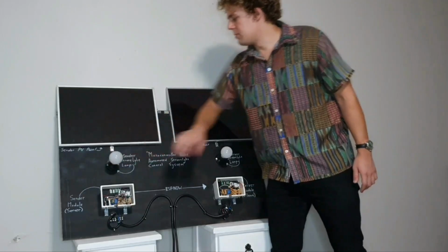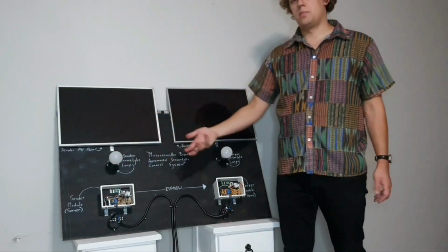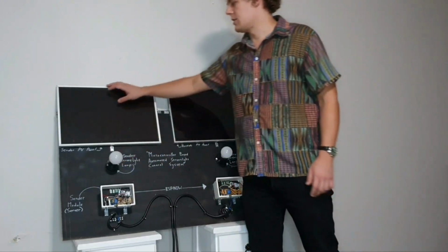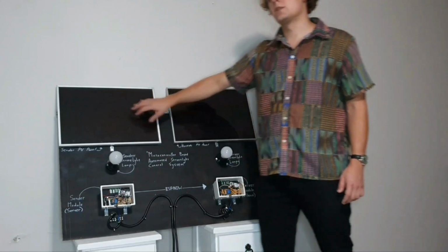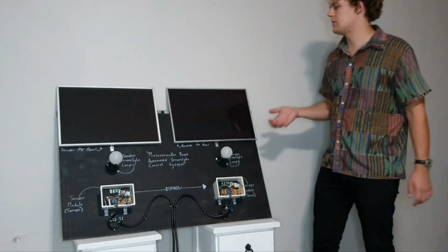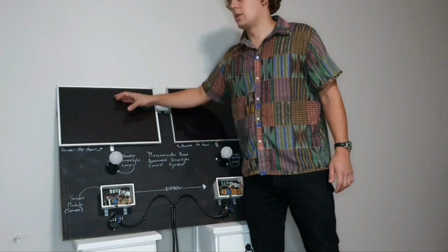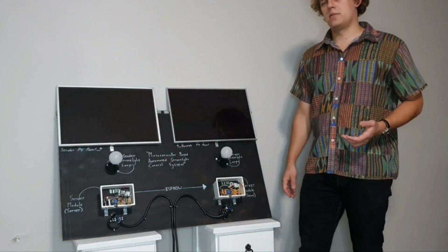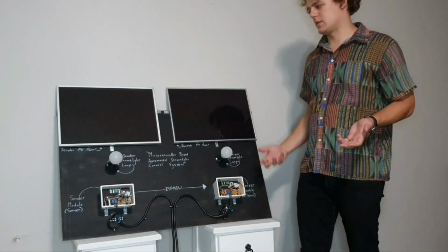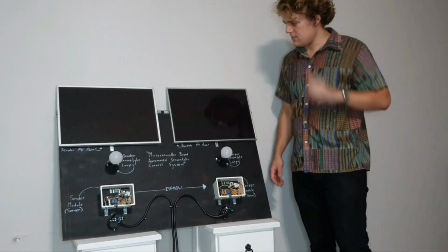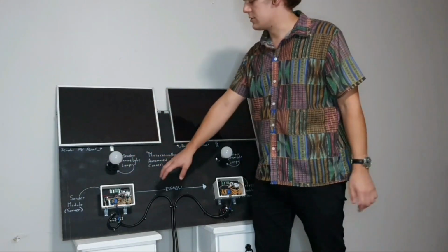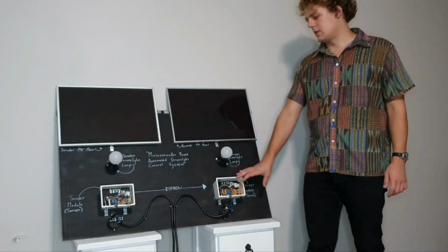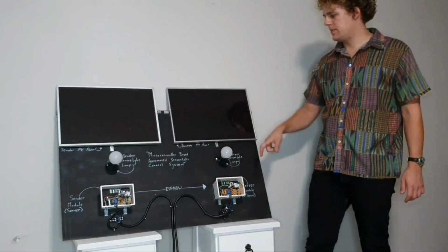So the light bulbs over here, they imitate streetlight bulbs. So these are 6-watt LED bulbs. And the solar panels over here are used for charging the system. So at the moment they are not in use, but during the daytime they can charge the system and ensure that there's enough battery life left during the night time when the system is operational. The system uses a relay to switch each of these lights. So there is a 5-volt 10-amp rated relay inside of each of these modules.